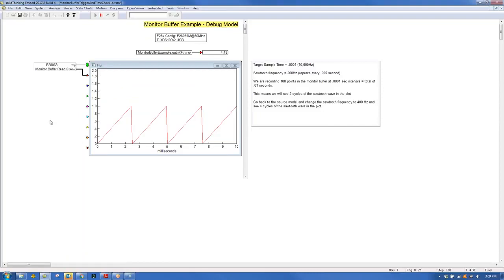So this is a very accurate way to capture the data off the target interface. It's essential for doing any kind of work on the target interface. At the motor control level, you're going to need to have this kind of accuracy to ensure the PWMs are working properly and that your sensors are working properly, and to be able to see it and plot it out.